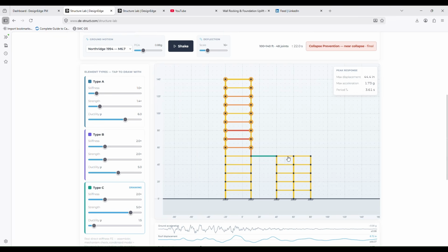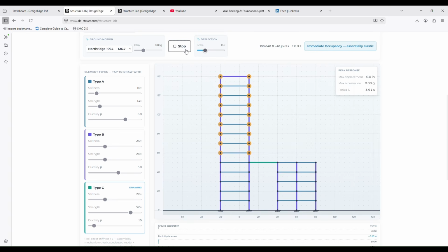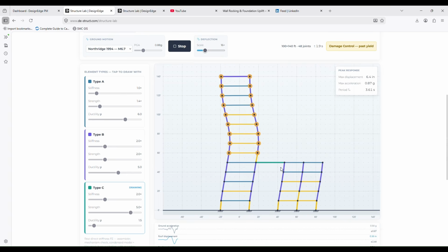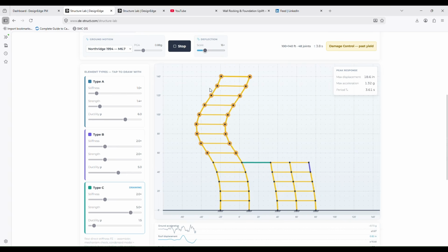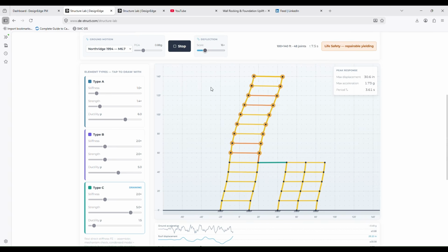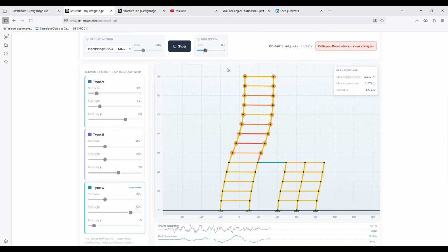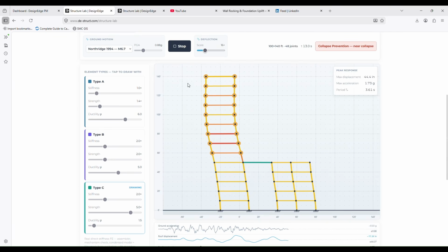So this is a significant stiffness discontinuity, and this upper portion was almost acting like a secondary building. And when you shake it, what you'll notice is the period of this, how it's influencing the higher mode responses of the structure over here. So it's that combined period which is throwing more amplification in the taller structure up here.